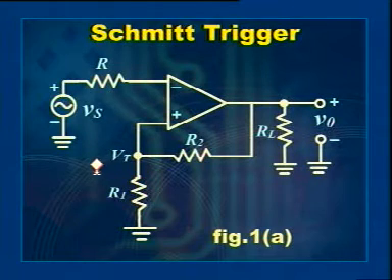Now let us take up a special voltage comparator, that is the Schmitt Trigger. Here in the Schmitt Trigger circuit we use positive feedback, and this circuit is also known as a regenerative circuit. The Schmitt Trigger, also known as regenerative comparator, is shown in circuit diagram 1. It consists of resistors R1 and R2 which are connected from the output terminal to the non-inverting terminal. So, the voltage across R1 acts as reference voltage at the non-inverting terminal. The reference voltage here is mentioned as threshold voltage level Vt. As in figure 1, the threshold voltages are obtained by using the voltage divider R1, R2.